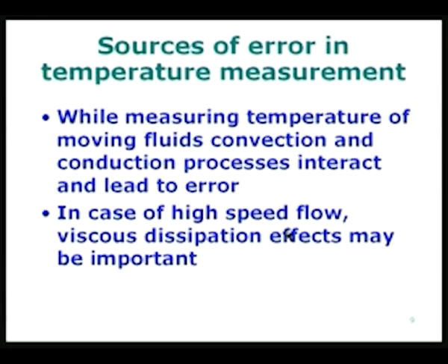In case of high speed flow, which is involved in aerospace applications, viscous dissipation effects may also be important. That means the conversion of kinetic energy of the fluid to internal energy, and when kinetic energy is converted to internal energy because of viscous forces, the temperature will go up.